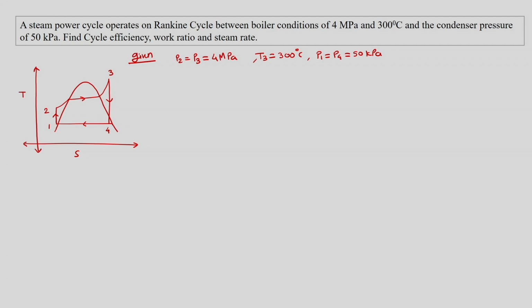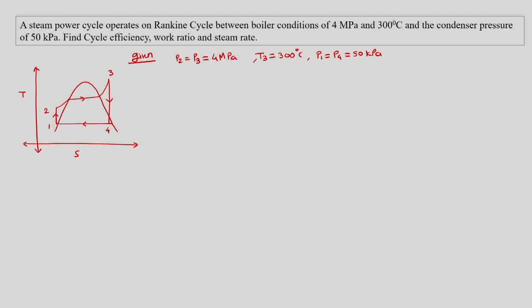So in view of this, we can proceed with the example, and here we need to first go to the steam table and then find out what are the properties at different stations. What properties we can find out from the steam table? We can find out definitely the property 3, okay, and property 3 would correspond to, if I go to the steam table for the 50 kilopascal.